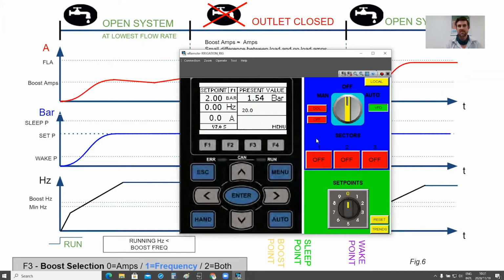So here's my system. If I enable one of my field valves, you'll notice my pressure would drop drastically, and then I'll enable the drive to run in automatic mode. So while I'm below 1.5 amps, I'm detecting boost. But as soon as I go over 1.5 amps, that timer will stop detecting there's no load. So I'm happy that I'm running above load with over my 1.5 amps. This is a small pump, so amps, in my opinion, is not the best to detect on, but we have just enough differential to use it in this scenario.